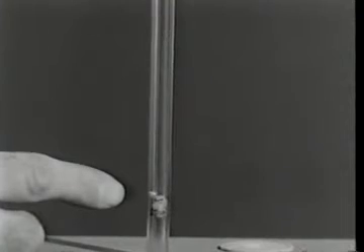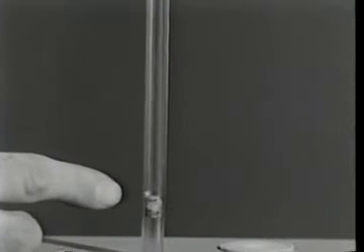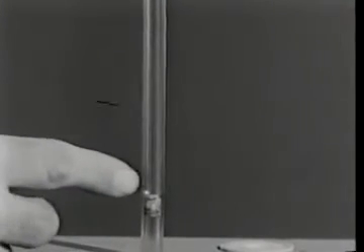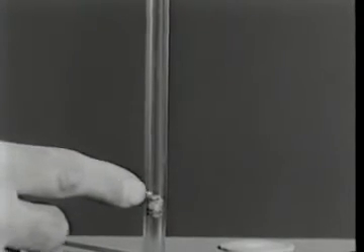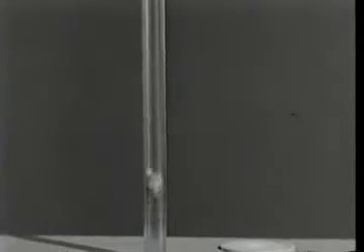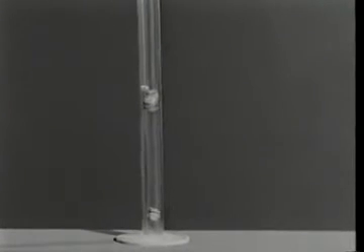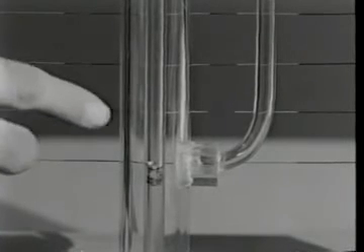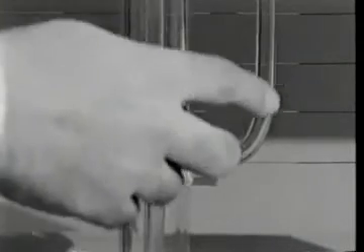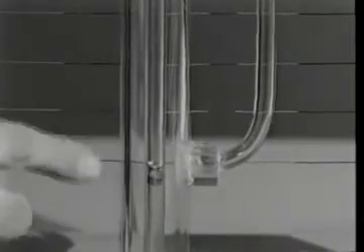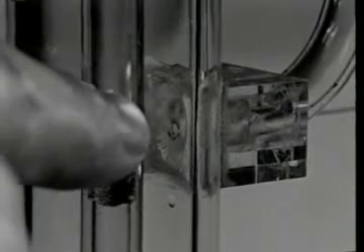The force per unit area exerted by the fluid in the direction normal to this cylindrical surface will be indicated by the level of the fluid inside this manometer tube. The stress normal to the outer cylinder will be shown by the level of the fluid in this sidearm manometer tube attached over a hole in the outer cylinder.